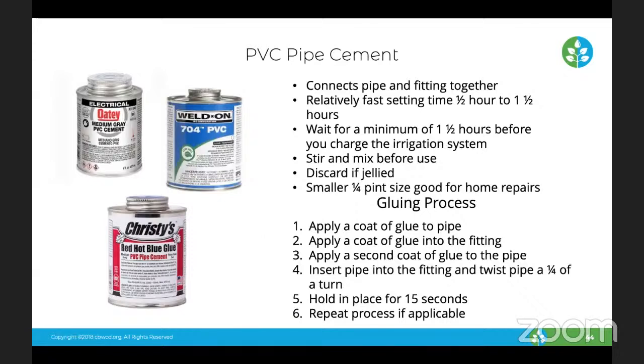One thing though I would recommend, if you are going to do some repairs at your home, or if you're going to do an installation, always opt for the smaller cans of the glue and primer, especially the glue, because the glue will dry over time. If you don't use it all, when you go to use the can again, you might find that the glue is not as malleable. It's not as liquid.